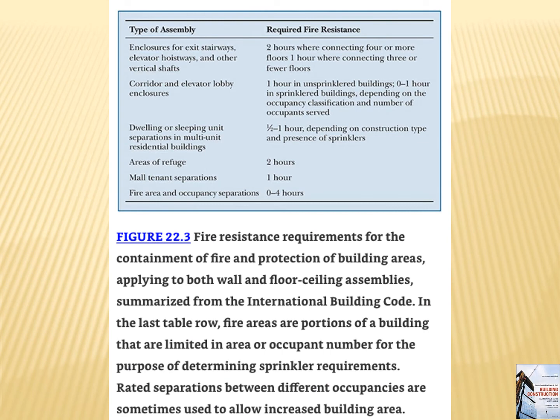Fire resistance, you always want to be concerned with that in any building, but if you have a large occupancy to the building, this is a very important part of the building code. You need to get this past the fire marshal in your drawings, and you very much need to consider people being able to get out of the building and survive based on the fire ratings of the different materials, how long it takes for the fire to burn through.